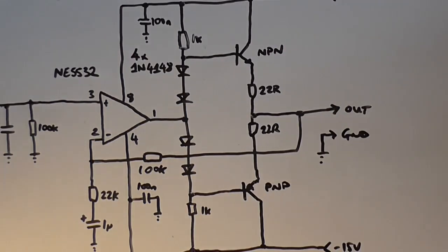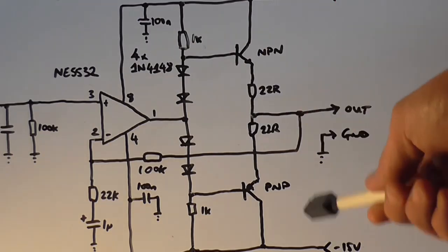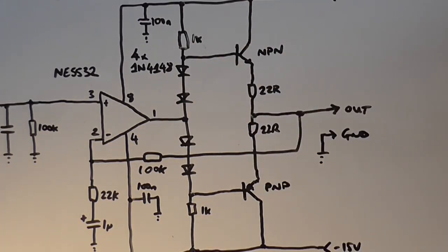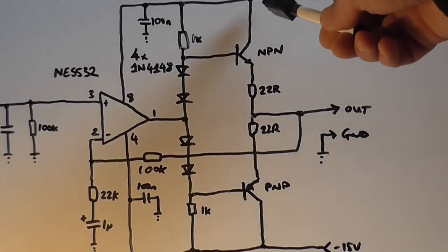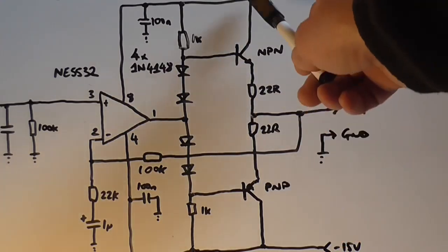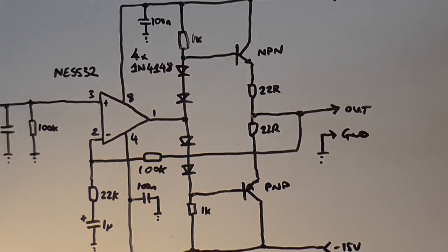Keep that in mind. And also, if you were to use this in a higher power sort of arrangement, where the output transistors had their own separate higher power supply, like a plus minus 35 volt, I would strongly recommend A, having inline fuses with each device, and B, I wouldn't use this topology with single transistors.